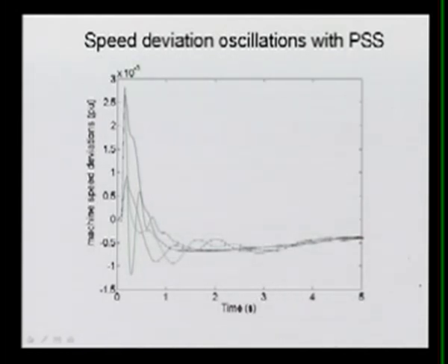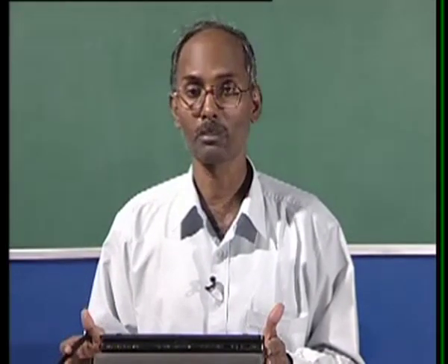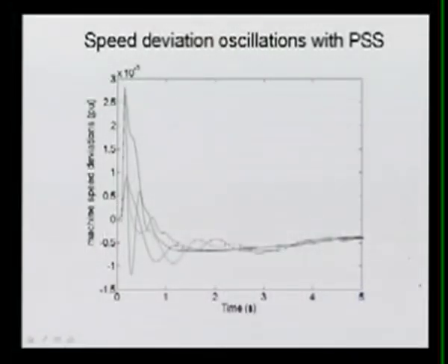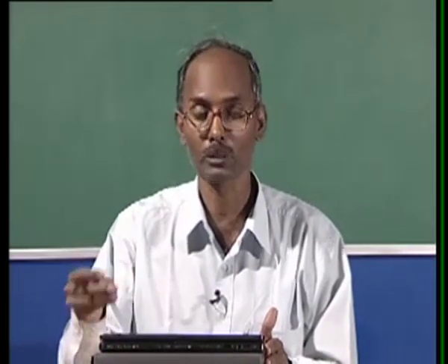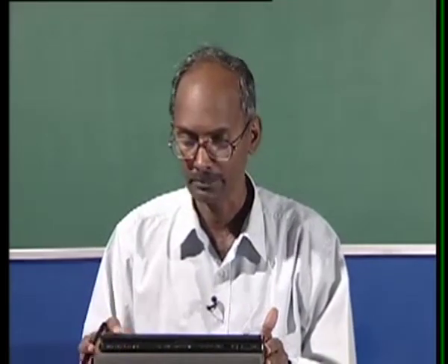So this is the beauty of the power system stabilizer, but the only problem is that if you are using a power system stabilizer, the gains as well as the time constants must be tuned, meaning the parameters of the PSS must be obtained clearly for a wide range of operating conditions. That is why in our country we have generating stations equipped with power system stabilizers, but these units are isolated from the system because they are not tuned properly, and once they are put in the system, instead of stabilizing they are going to destabilize. So the tuning is very, very important.